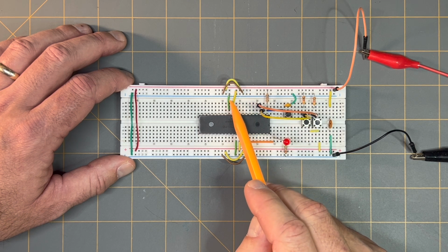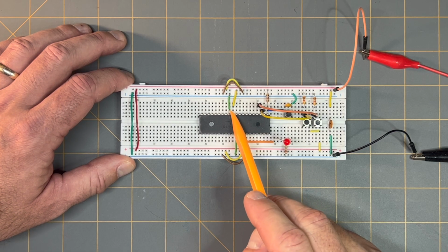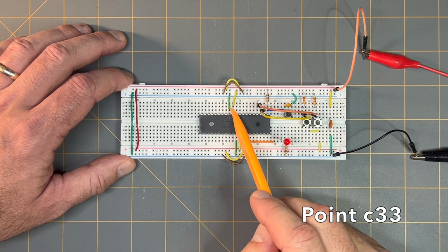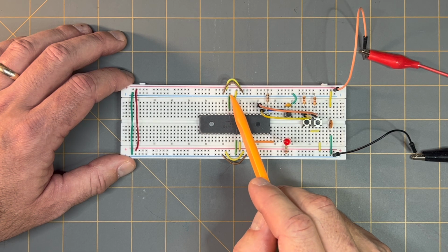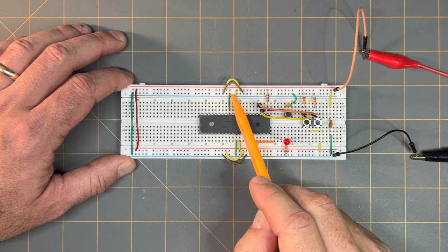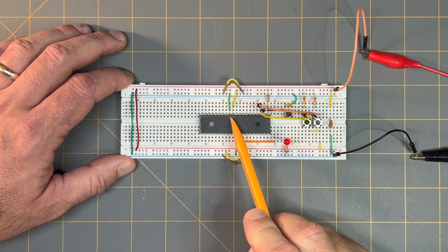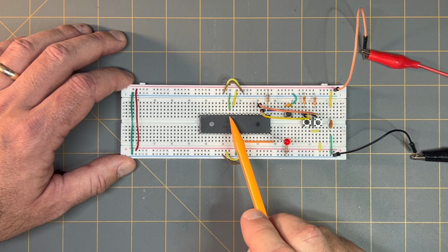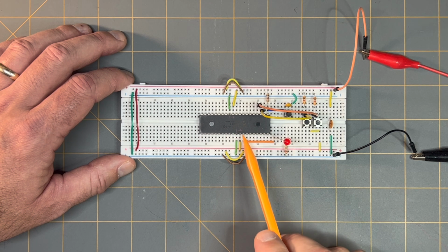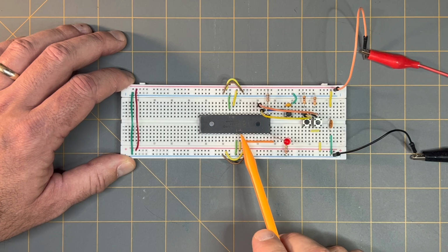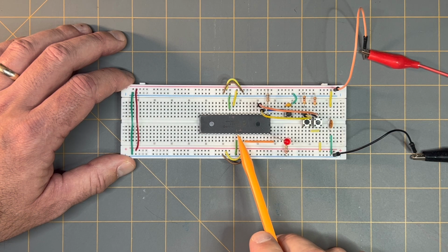And then I connected the negative supply at point C5, I believe that point is, and the other end of this green jumper wire is in a point on the negative power rail here, and this green jumper wire is in line with pin 12, and that is for the negative supply to the PIC microcontroller. And similarly, on this side of our positive and negative supply to the PIC microcontroller, to pins